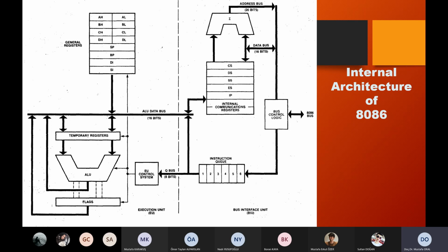The bus interface unit brings this information into the microprocessor, and inside there is a decoder. By looking at the opcode, the electronic device understands that it has to initiate a certain routine to accomplish what the opcode tells the microprocessor to do.